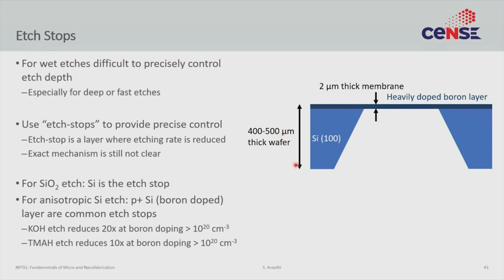So of course, this means in order to go 400 micron, 400 by 6, you need essentially 60 hours. Now, if you are doing an etch of 60 hours, you leave the wafer and walk away, and you come back after 2.5 days. If the etching times are that long, it's very, very hard to precisely stop at say 2 micron thickness, because you are etching 500 micron and trying to stop at exactly 2 micron. That's just a very hard processing problem.